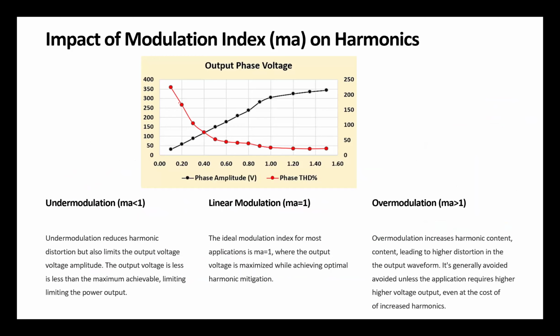Okay. Now we said frequency is one of our degrees of freedom, to manage switching frequency. Why am I insisting on switching frequency as one of the leverages that we have, and not reference frequency? We can't control the reference frequency, but we can control switching. You can't control the reference. This is what we create. This is our signal. We create the reference signal, we create the carrier frequency.